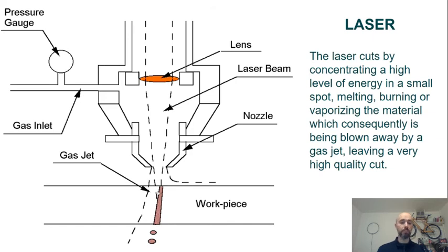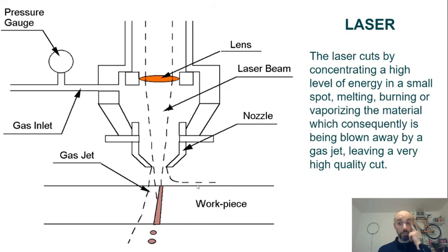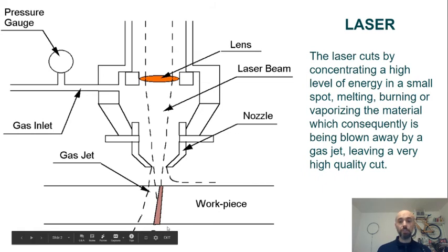Now, the second reason why we have this flow of air: in some materials, it helps the process. For instance, with wood or other materials that burn, the oxygen that we blow through the air is actually speeding up the burning process where there's enough energy to cut it and burn it away, and cool down and turn off the fire, let's say so, on the borders, on the part where you don't have enough energy to actually burn away the material.